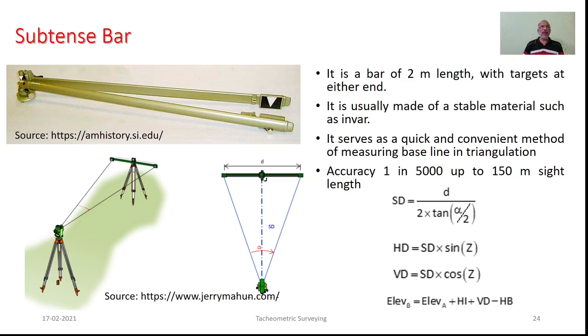Just a last comment, as we discuss this particular tachometry as a technique. The technique as such is very helpful. It is an optical distance measurement method. But the way you see, here the multiplying constant is 100. So say, if that particular staff intercept is erroneous by simply 1 centimeter, it will be reflected 100 times, and hence the distance measurement will be that erroneous.